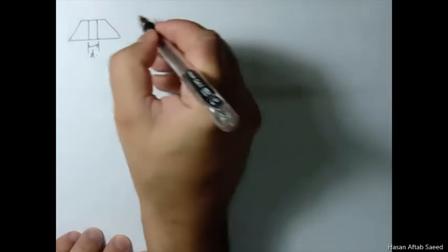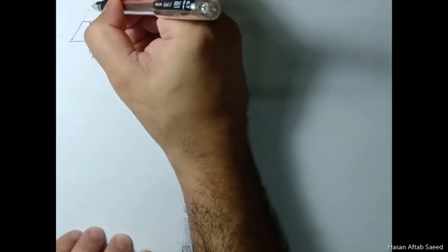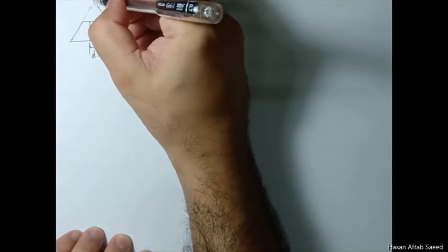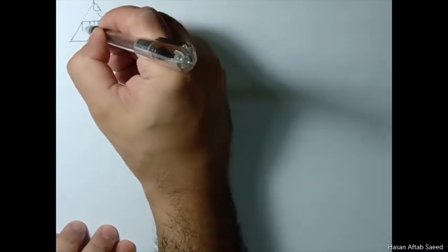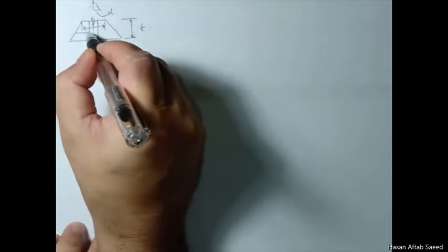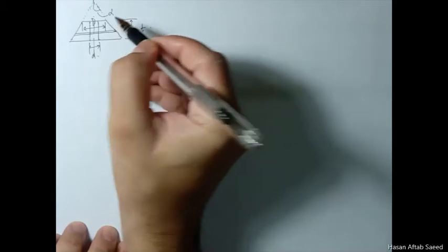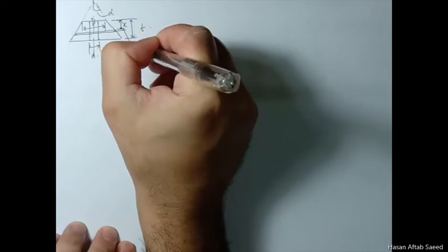this is d. Let's say the thickness in this case is t, and the angle of this cone, actually it's a truncated cone, but for the complete cone, half of the angle is alpha, and this distance, let's call this capital D. Now because this area keeps on changing, we'll take a small differential slice here, at a distance x, and the thickness of this slice is dx.